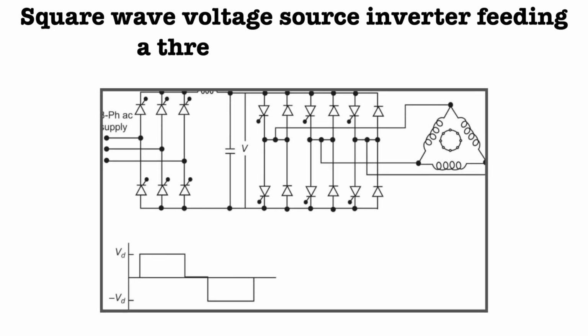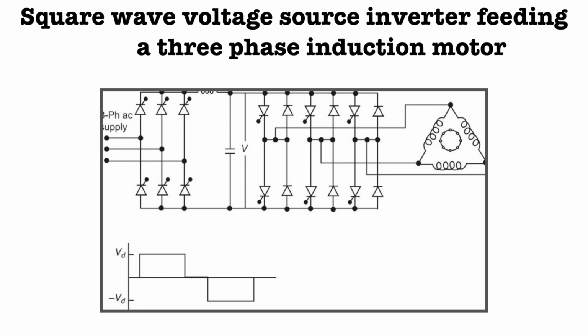The variable frequency required for the speed control of three-phase AC motor is obtained from a three-phase inverter. To avoid magnetic saturation and to obtain constant flux condition in the machine, the voltage fed to the motor must be varied.